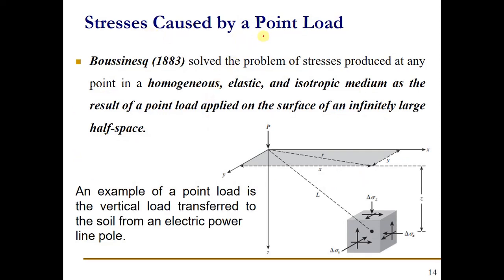Starting with the stresses caused by a point load, Boussinesq in 1883 solved the problem of stresses produced at any point in a homogeneous, elastic and isotropic medium. The assumptions are very big, that the soil is homogeneous, elastic and isotropic, but the practical significance is there to make those assumptions.